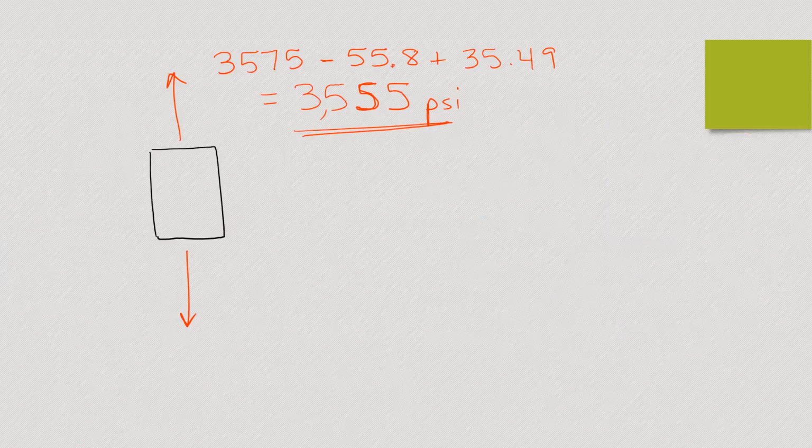Now, for completeness, this problem would also have PR over T in that other direction, but it shouldn't have any other stresses in that direction. Okay. And nothing in this problem would cause shear. All the loading was symmetric, so there wouldn't be any shear caused. Any questions about that procedure?